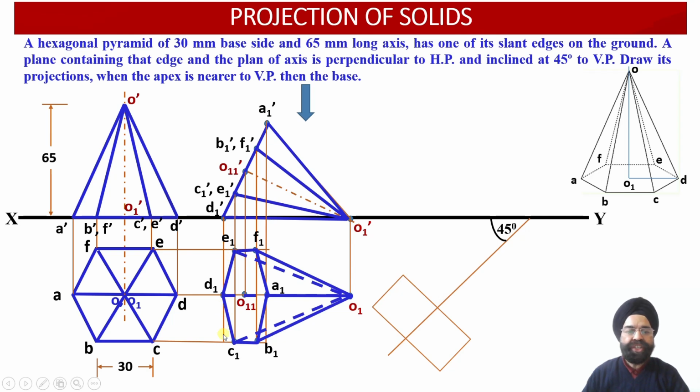So this is the longer edge. We have drawn the longer edge over here. This is the shorter edge of this rectangular construction. Again, the shorter edge has been constructed over here using rectilinear projection transfer. Now we can see between these two edges we have got point 1, point 2 and point 3. So we can measure the distances of point 1, point 2 and point 3 from the extreme ends over here. So these three intermediate projection lines we have drawn over here.